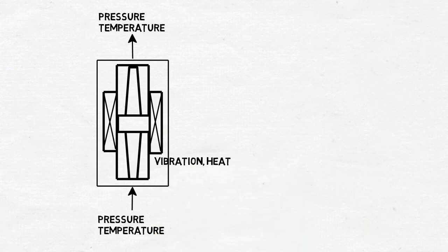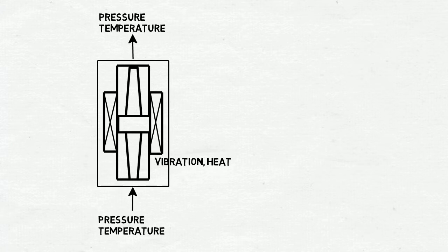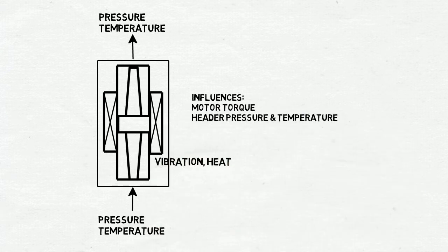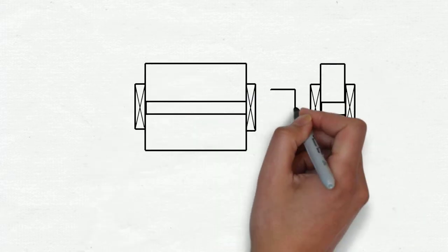Other variables we will want to include in a pump model due to their influence effects are pump header pressure and pump header temperature, and also motor torque if available. Next, let's consider the bearing temperatures and lubricating oil system.